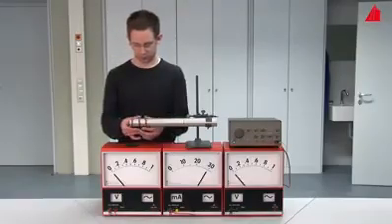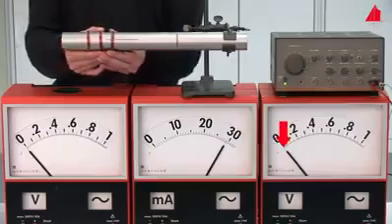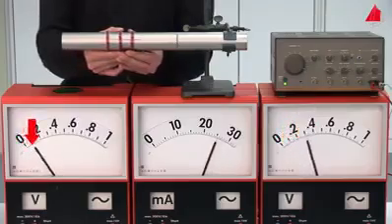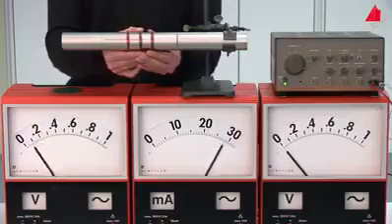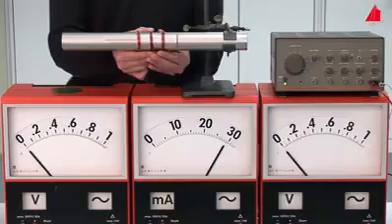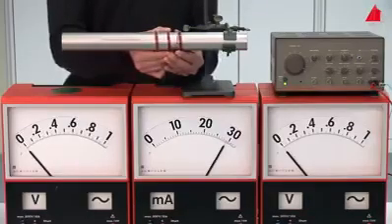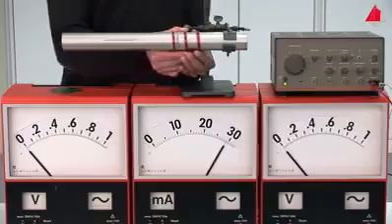He carefully takes all three coils and moves them to the right. The pointer of the right voltage meter deflects, then the pointer of the left voltage meter. Further to the right, where the tube is intact, the pointers of none of the voltage meters are deflected. Unfortunately, the saw cut in circumferential direction is again not detectable.